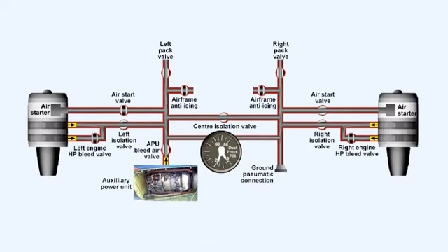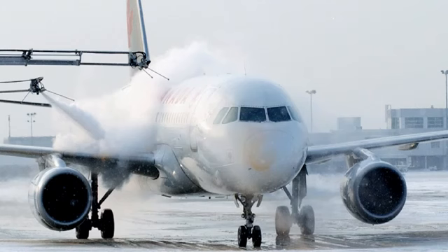A shortage of sufficient cooling air can be caused by the engine not rotating fast enough, maybe because the duct pressure is too low to drive the starter motor at the required speed. Slow engine rotation could also be caused because ice accretion within the compressor annulus has caused a partial seizure of the compressor.